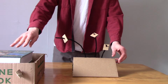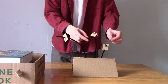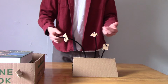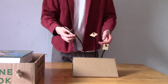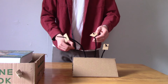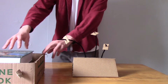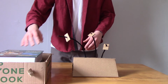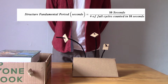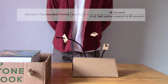So now we've constructed our model of an earthquake and our model of 3 different buildings. You'll notice that I put little pieces of cardboard on this. You can change how high up on the pipe cleaner this is to adjust the frequency that the modeled structure vibrates at. So if you move it higher, it'll take longer to vibrate, and if you move it lower, it'll move quicker. What you want to try to do is make it so that one of yours, preferably the center one, moves at about the same speed that your model earthquake moves. Now is a good time to use this equation to calculate the period of each of your structures, ensuring that your center structure matches that or is very close to that of your earthquake.